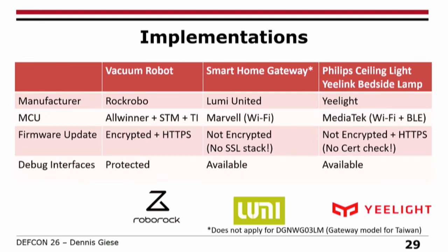Another vendor, Lumi, has a smart home gateway, and they use this Marvell chip, this Cortex-M chip that I told you about, and they don't encrypt their firmwares at all. And the thing here is they don't even have an SSL stack in their firmware. So even if they wanted to use SSL, they can't because the firmware doesn't support it. And the debug interfaces are open here. So JTAG, everything is there.